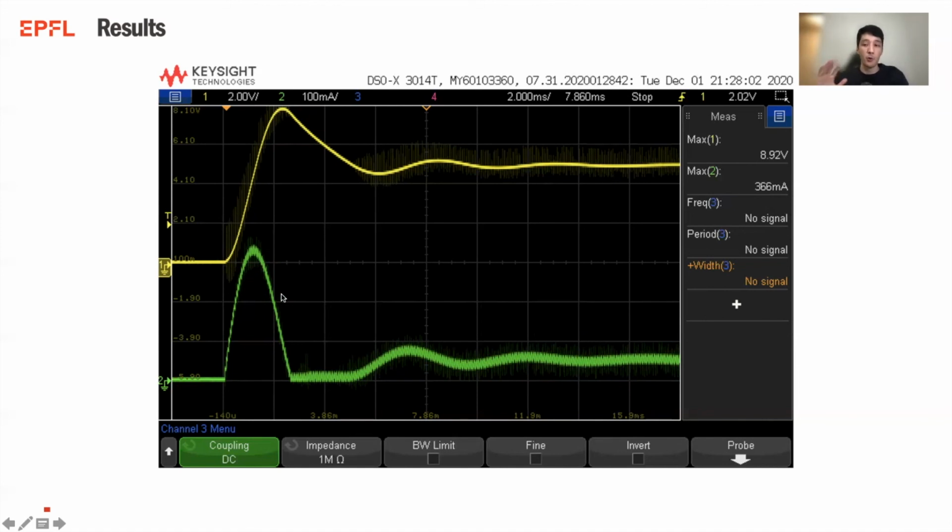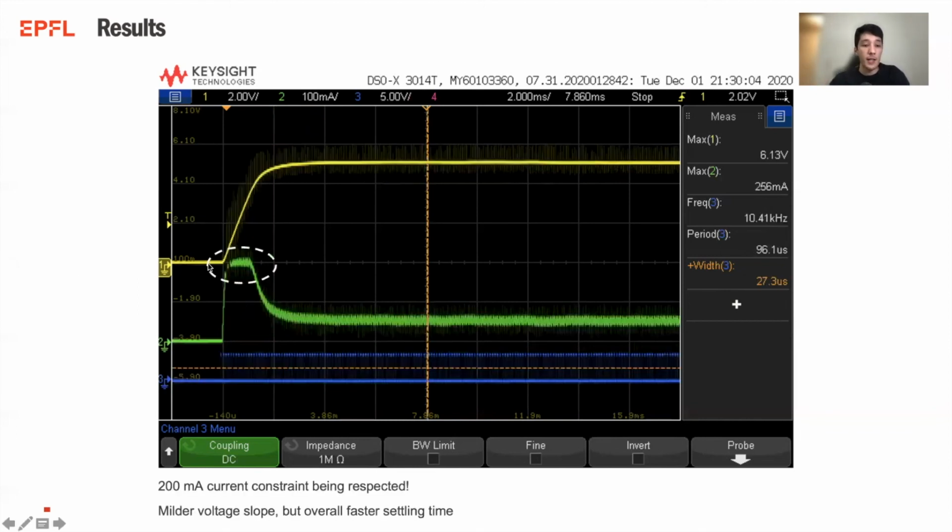Can you now improve this transient response using MPC? Yes, that's very much possible. This is what you see on your screen. The voltage waveform goes up and it's even monotonic, so there's no overshoot. It converges faster to the steady state value. The current rises and then it hits the constraint. It's 100 milliamps per division, and that's 2 divisions, so it hits the constraint that we had defined, 200 milliamps. And then it goes down to the steady state value. So overall, this looks much, much better than the open loop response.